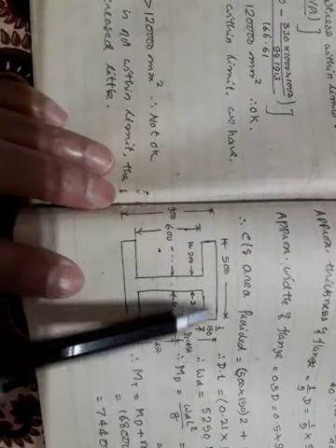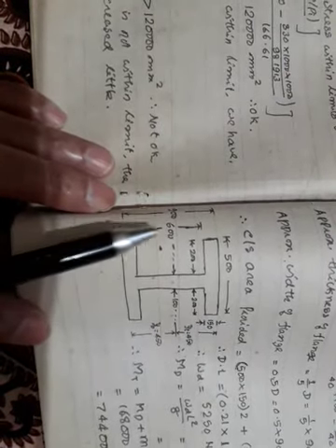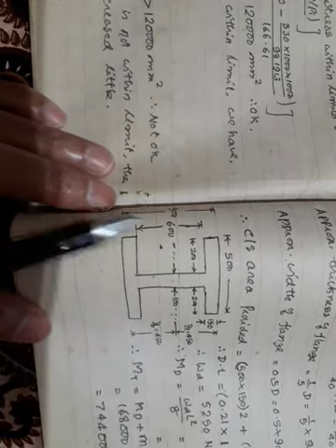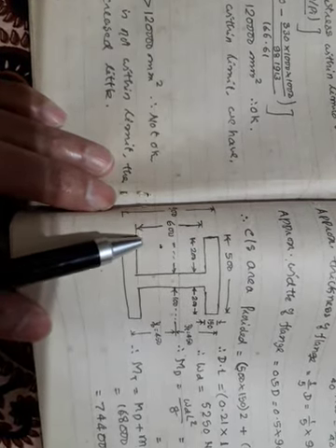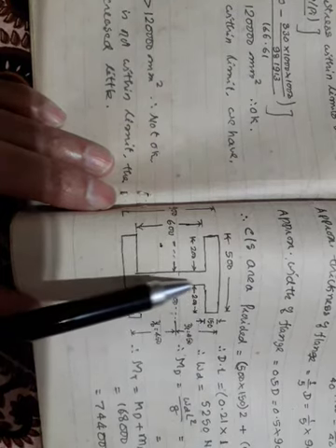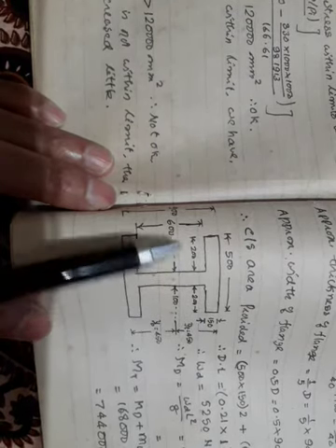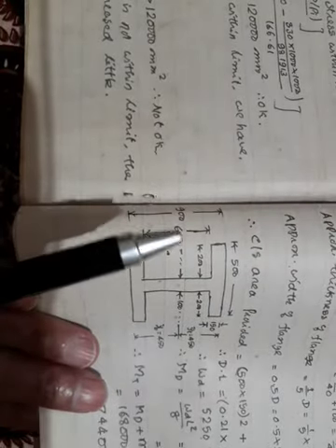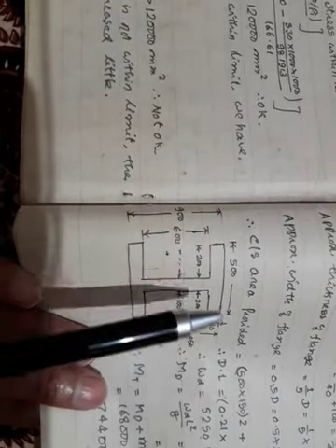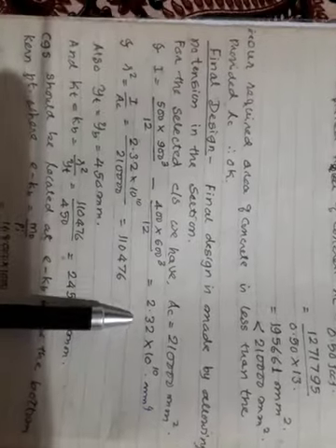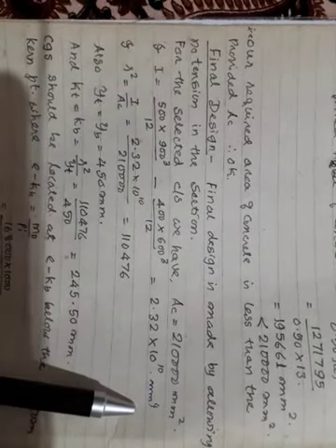While calculating the moment of inertia, what I have done is, I am considering this as one rectangle. From this rectangle, I have deducted these two rectangles, this one and this other one. Either you can do that, or otherwise you can go for it individually. Both can be done. So I can be easily calculated. It is 2.32 into 10 to the power of 10 mm fourth.